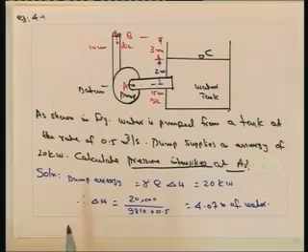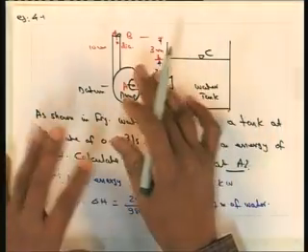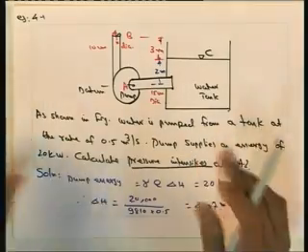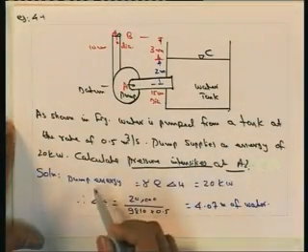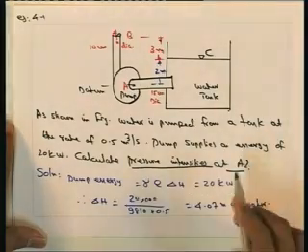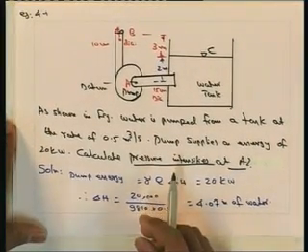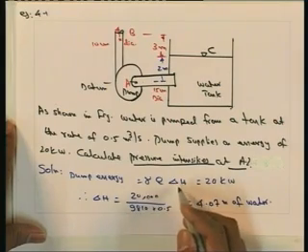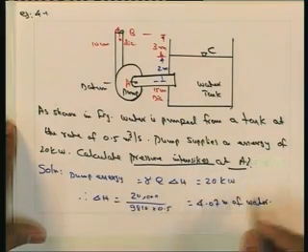Here, even though there is a pump attached in the problem, we can still use Bernoulli's equation. First, the pump energy is given as 20 kilowatt. We have already seen the equation for pump energy as gamma Q into delta H. So gamma Q delta H is 20 kilowatt.